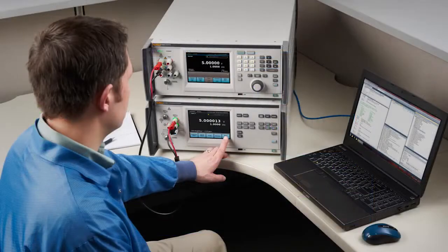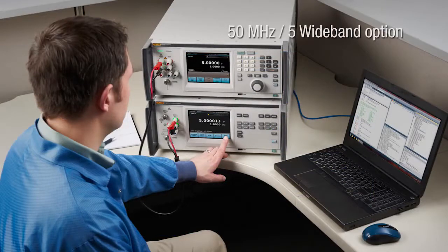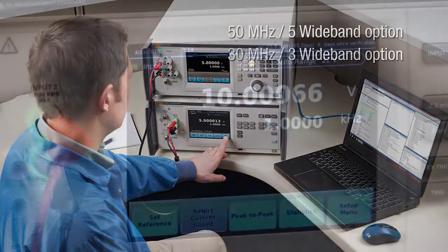The fourth major improvement is the addition of the 50 MHz wideband option that extends the bandwidth to 10 Hz to 50 MHz for calibrating precise RF power sources. Like the 5790A, the 5790B still offers a 30 MHz wideband option, ranging from 2.2 millivolts to 7 volts, and with a frequency range of 10 Hz to 30 MHz.